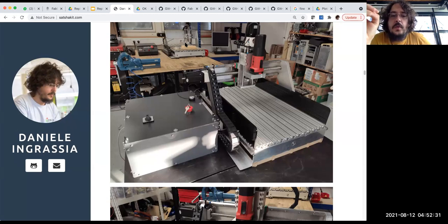Now you ask me what I can do with only 60 millimeters Z-axis. I mean, of course, I can do molding and casting, I can do PCBs and so on. But what if I need to engrave a big piece of foam, for example, or I need to have something that is longer? Because in the 60 millimeters, you have to consider also the body length of the tool. And if you put the tool below the holder, the 60 become maybe 40 or 30 millimeters, and it's super limited. So in our machine, we have 150 Z-axis. So it's more than double the Z-axis of the other machine.